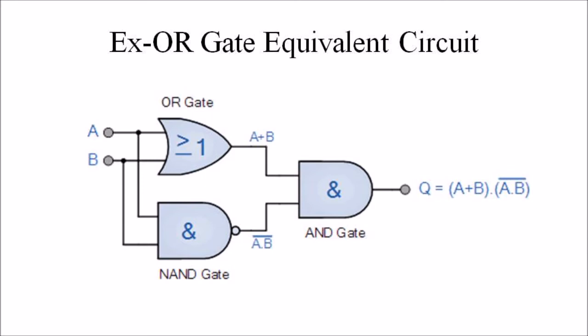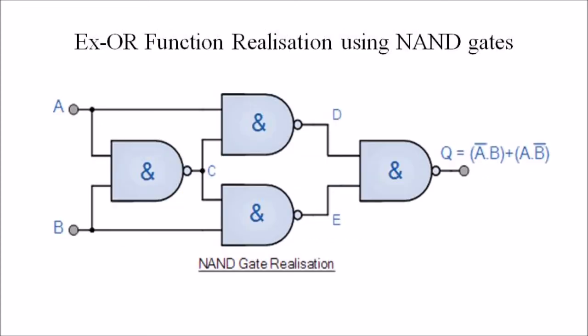Here in the circuit we can see a combinational logic. One of the main disadvantages of implementing the XOR function in this case is that it contains three different logic gates, OR, NAND and finally AND, within its design. One easier way to produce an XOR function from a single gate type is to use our old favorite NAND gate, as shown in this figure.